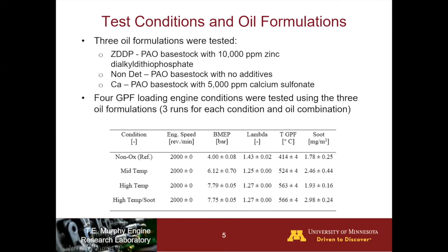The test conditions and oil formulations, we tested 3 oils. The first one is ZDDP oil. So it's 100% PAO base stock with 10,000 ppm of ZDDP. A non-detergent oil that was just 100% PAO base stock with no additives. And then a calcium oil, same PAO base stock with 5,000 ppm calcium sulfonate.